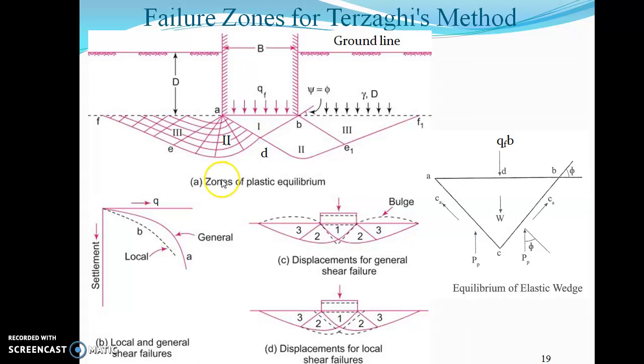Then the material yields. Now in our case, the material is soil. The soil will yield. Once the soil yields, the deformation will continue, and this time it won't be proportional to the stress increment. Sometimes you may not even require incremental stress. Deformation may just go on continuing in absence of additional stress.